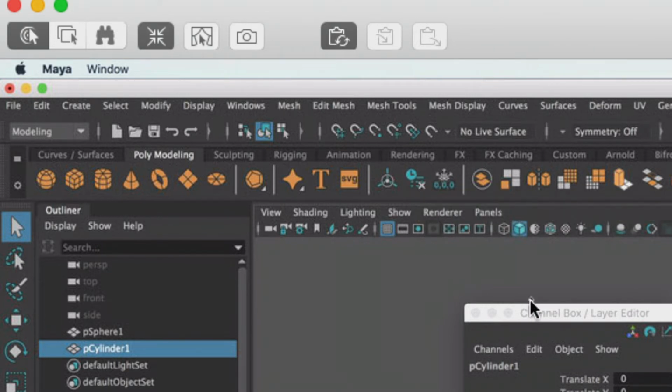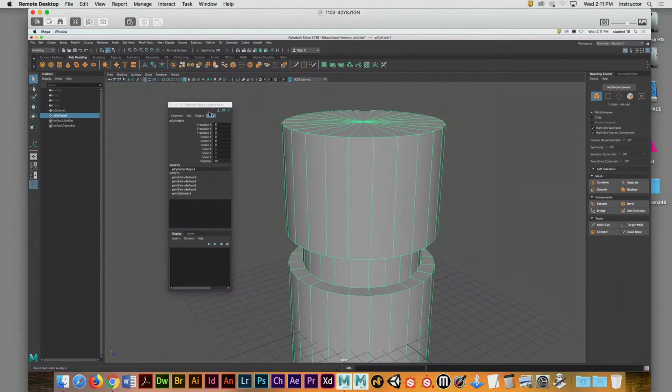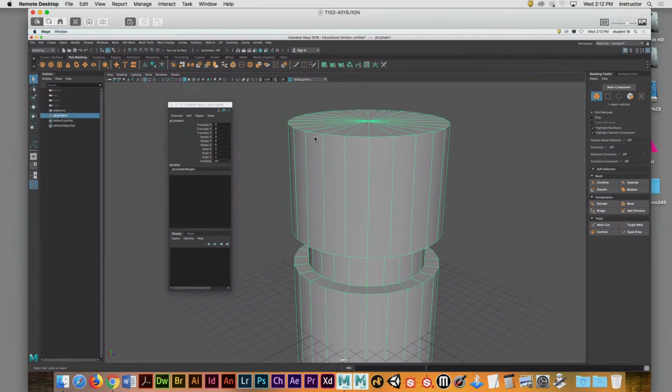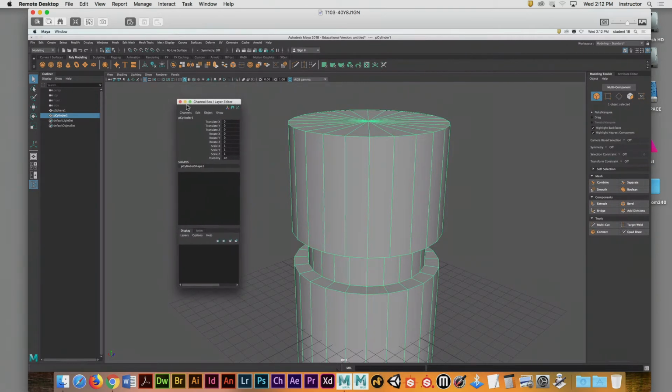So I've got my little cylinder thing selected. Delete by Type. Bloop. You can see all those poly inputs go away. We've deleted them. They're no longer available for evaluation. And now we're a step closer to making a true independent non-reference mesh. There's no inputs influencing the geometry here, so we don't have to worry about the past influencing the future. It takes a little getting used to, this input, this object history, but it's not too bad when we get right down to it.